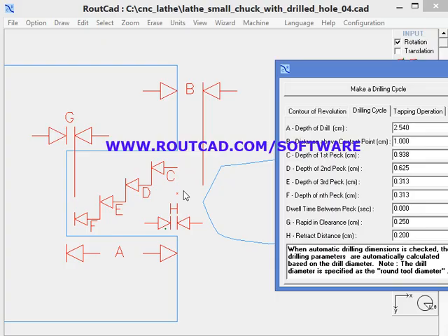Then it will switch to cutting speed. It will go to the contact point at cutting speed, or basically to the distance G above the contact point at cutting speed, and then it will go in the material depending on which peck it is doing. Now we also have an end peck. If the material is very deep, the tool will actually go in the material at the end peck, and we could have many pecks following the last third peck. All the pecks will go at constant distance inside the material.